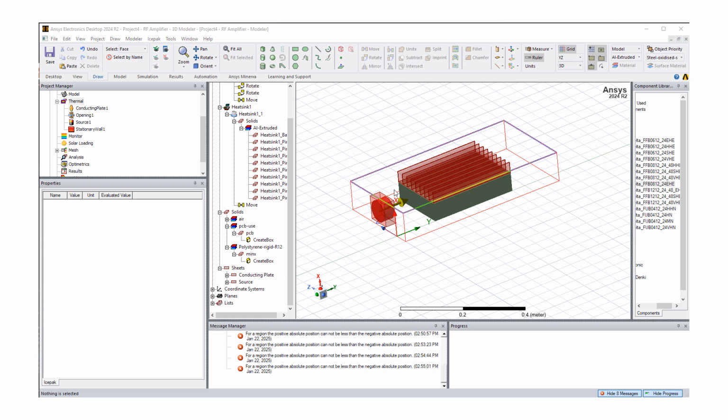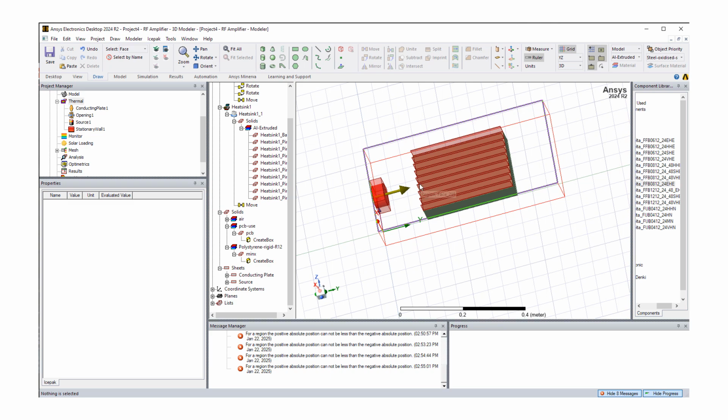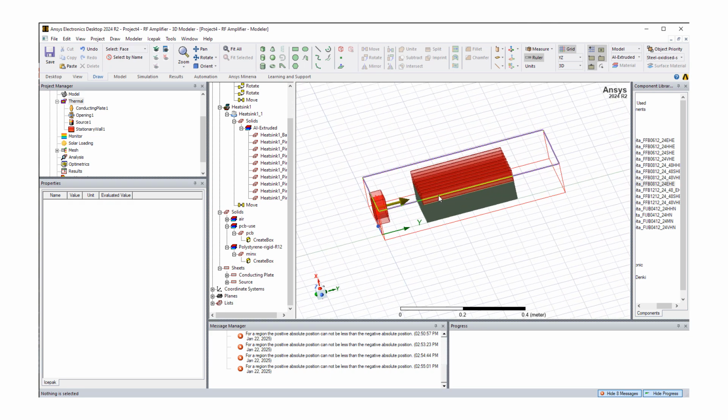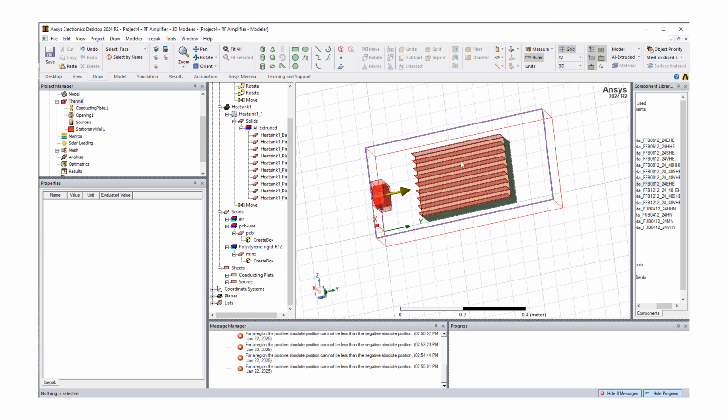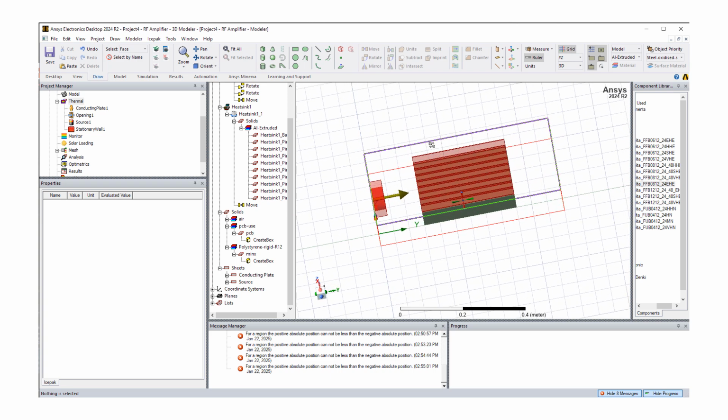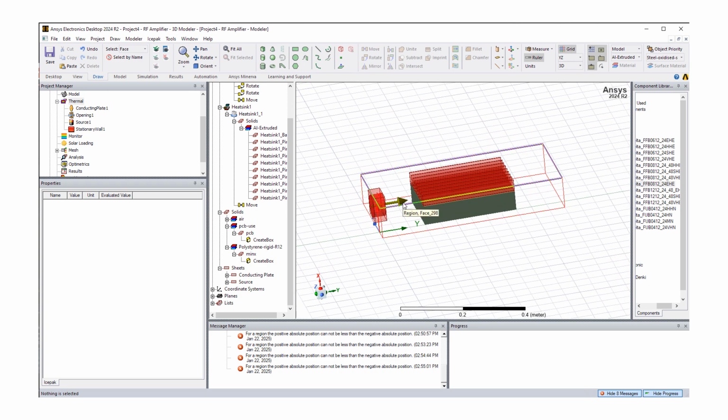In this video, first we're going to define some monitors where we want to track some flow and thermal parameters as the iterations go by to make sure we have convergence. We then are going to do some meshing operations. We want to have a good quality mesh near critical regions such as the heat sink and the fan to capture the flow and thermals adequately.